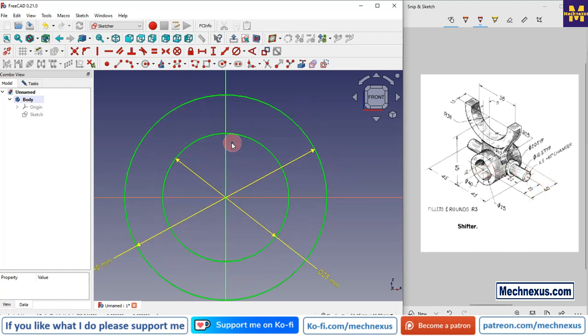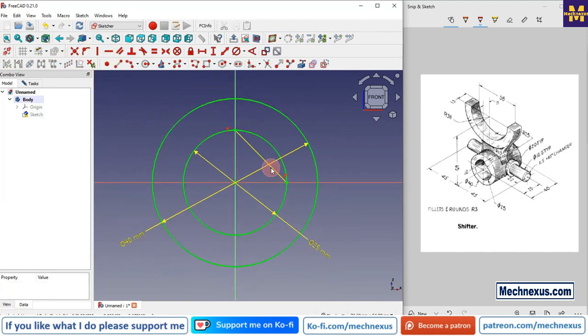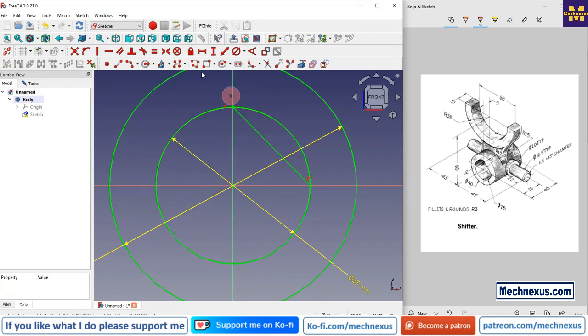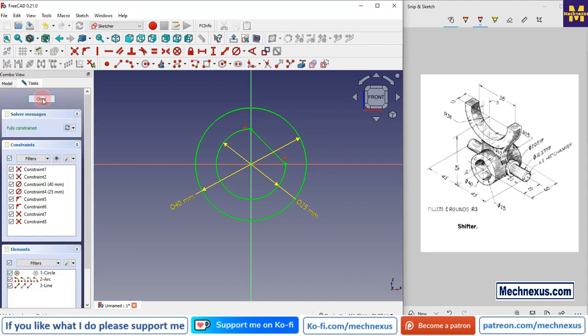and now here we will create a line, and this line has a coincidence relation with this circle. Now we will give this relation with the axis as well. Click on coincidence, click on coincidence, and now we will trim this unnecessary geometry. So click on trim and trim it, and we will come out of the sketch.